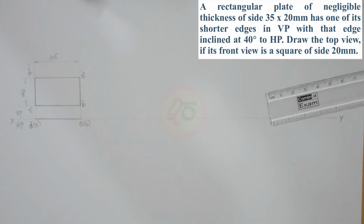Now, what did I say? We need to look for the relation with respect to the resting plane. Which is the resting plane? It is the VP. So, is there any angle given with respect to VP? There is no angle given. 40 degrees to HP: the relation to HP in terms of angle is given, but not in relation to VP.